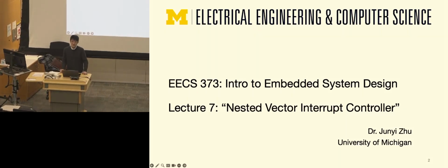All right, let's get started. Today we're going to mainly talk about the NVIC. Come on, guys, we're about to start. Today we're going to continue with what we left from last lecture around the interrupts. We're mainly going to look at the NVIC, the nested vector interrupt controller, which tells us what to do when multiple interrupts are happening, and what happens on the software level as well as on the hardware level.